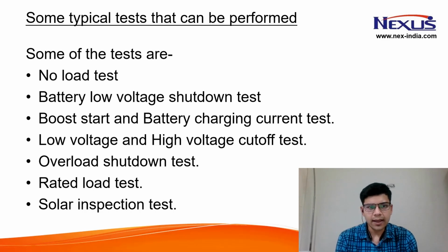Some of the tests are the no load test, the battery low voltage shutdown test, the boost start and battery charging current test, the low voltage and high voltage cutoff test, the overload shutdown test, the rated load test, and the solar inspection test. We are going to discuss each one of them in detail, one by one.